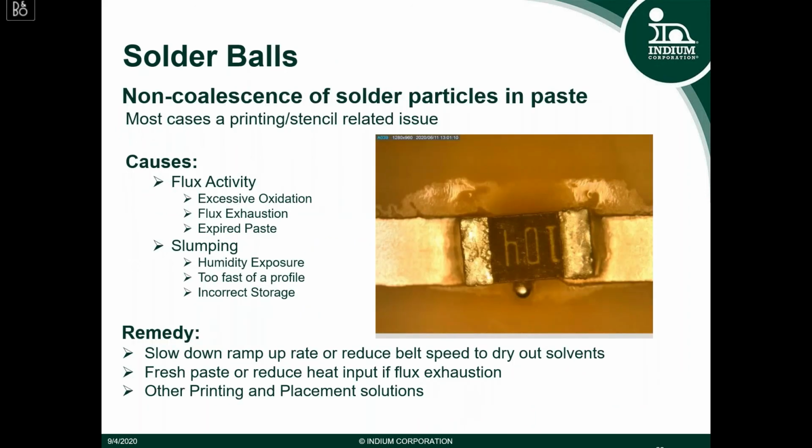And last but not least, solder balls. Solder balls are often referred to as mid-chip solder balling. In the image to the right, you can see where the two paste deposits may have connected under the body of the component. And then as the solder starts to melt, surface tension separates the two, but leaves behind a little bit of solder under the component, which squishes out to the side of the component, creating a solder ball. In most cases, this is a printing or stencil related issue, which can be mitigated or remedied from modifications to the stencil or optimizing the printing process.